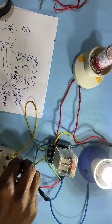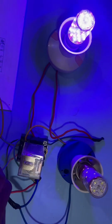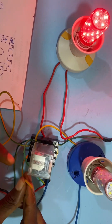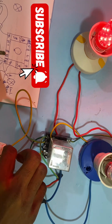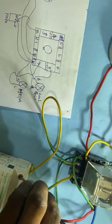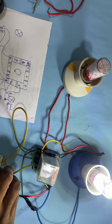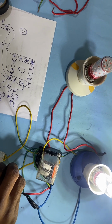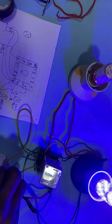So that is a simple automatic changeover using a relay. So that is just how the operation is. As you can see, this is a live terminal of my NEPA. So once the NEPA supply gives light, which is here, you see it will swap and leave the generator, turning the contact of the generator to normally open and connecting that one of NEPA. So I hope you understand the circuit diagram very well.